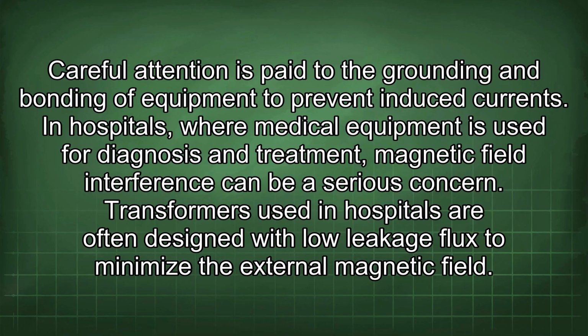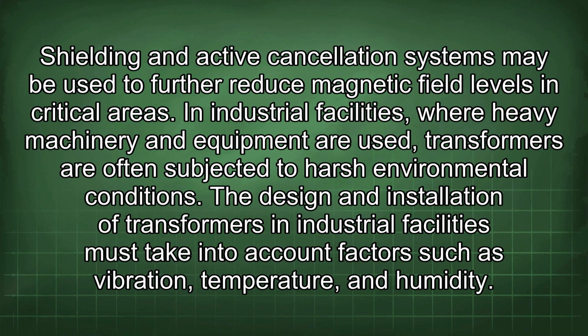In hospitals, where medical equipment is used for diagnosis and treatment, magnetic field interference can be a serious concern. Transformers used in hospitals are often designed with low leakage flux to minimize the external magnetic field. Shielding and active cancellation systems may be used to further reduce magnetic field levels in critical areas.